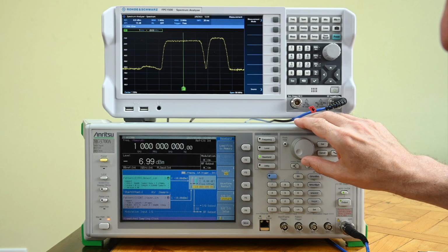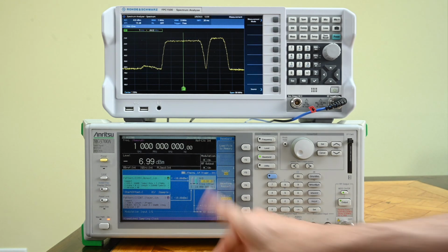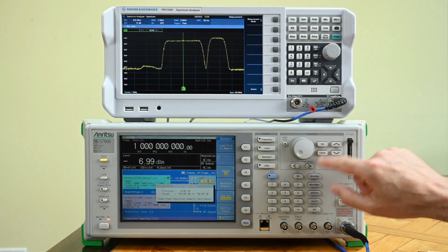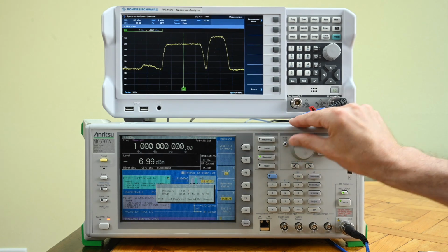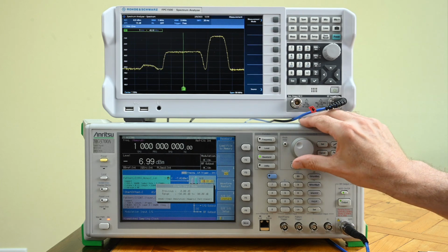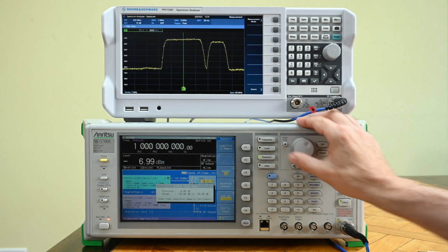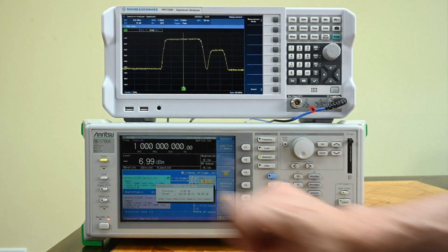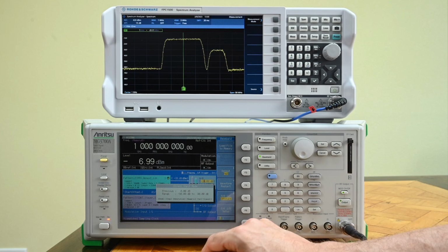And what we can also do is play with the relative power of them. Now we already set the power of them individually, but we can also set the ratio of power. With this ratio of power, let me move my cursor here to full dBs. You see, I can make one signal relatively weak compared to the other, or I can attenuate the other signal. What I think he's doing is maintaining the total overall output power of the device and only changing the ratio between them. And he does that by changing these two individual values that we saw before.